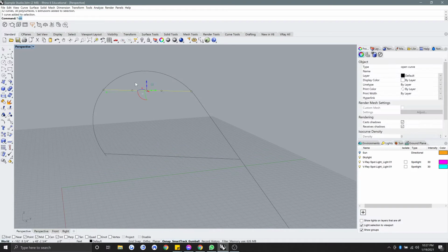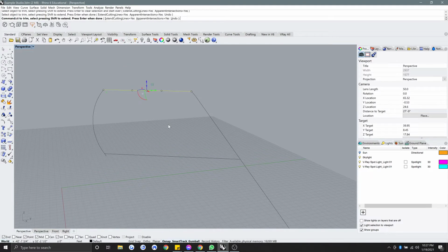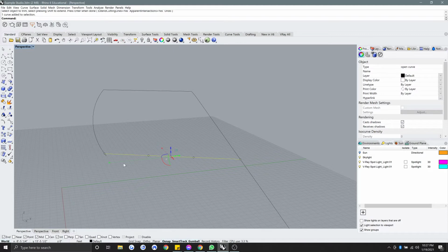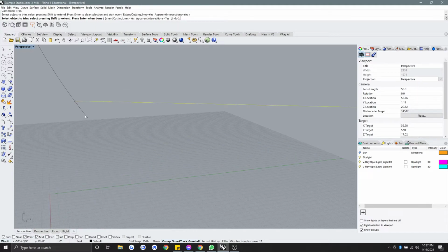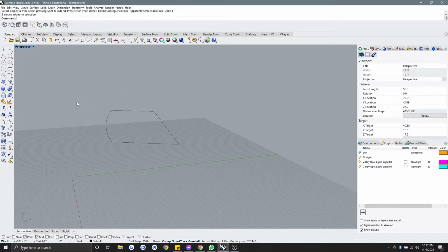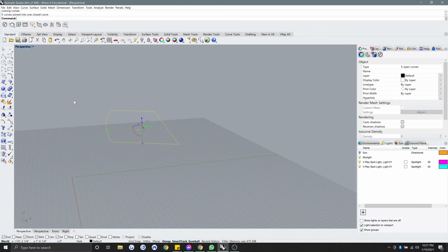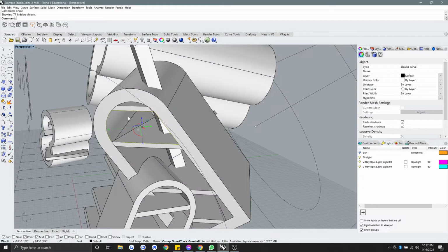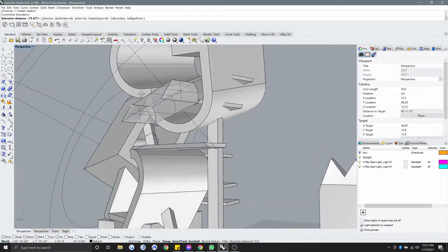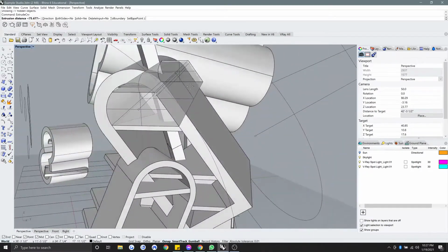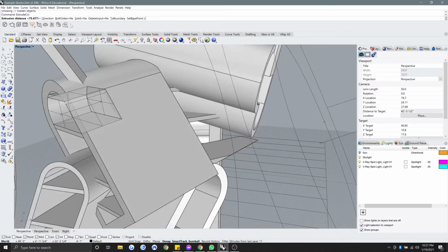At this point, I would trim the top off this, and I'm going to select this. I'm pressing spacebar to use the last command I used, which was trim. Again, that's my cutting line. I'll cut this line and that line off, which leaves me just with this kind of interior shape. I'll join it, type show to have everything appear again, and extrude this curve through. It wants to go at the angle that the shape is directed. I'm going to click direction because I'd like it to go along this flat plane, and click on this end